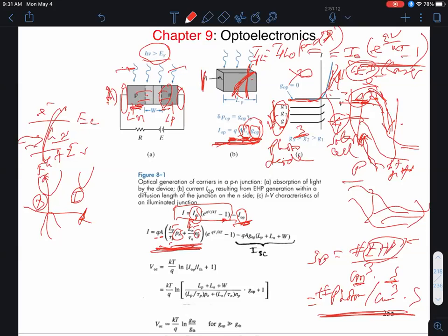You could also derive it in another way in terms of the gradients of the carrier concentrations. And there you get terms in the form of D_P over L_P and so on. Everything else is the same. Now D_P over L_P is the same as L_P over tau_P, because D_P times tau_P equals L_P squared. So this is the charge control way of deriving the equation. And this was the way we derived it first, in terms of the carrier distributions and the gradients. Do you remember that? Beginning of chapter 5.